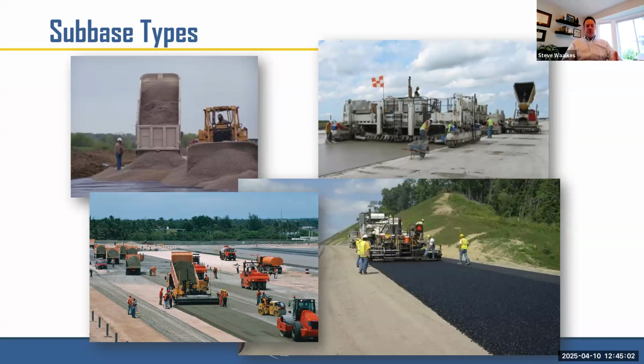If you have a very loose or bad subgrade material, just for constructability reasons, it will benefit the pavement's long-term performance, but really it's more of let's get out of the mud so that these subsequent operations don't get stuck. But we don't need thick or super dense layers underneath our concrete. We just need it to be stable, uniform, and drainable.